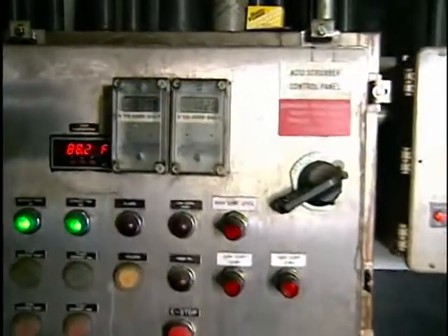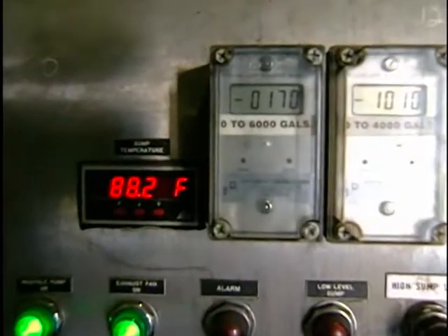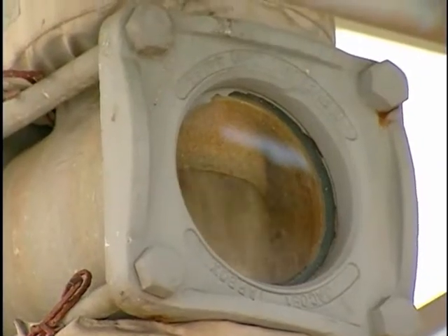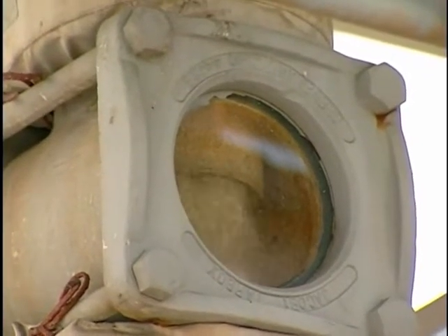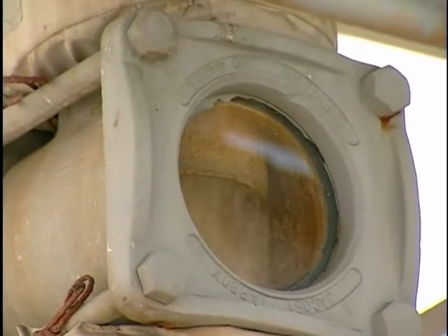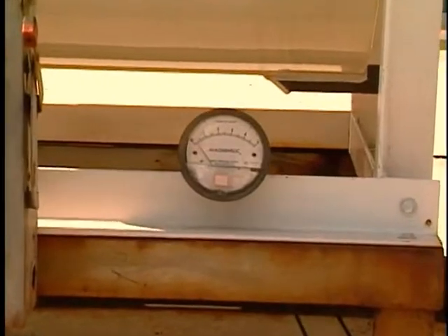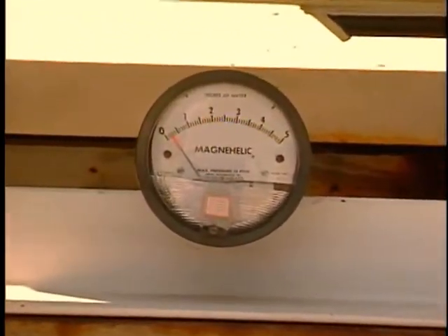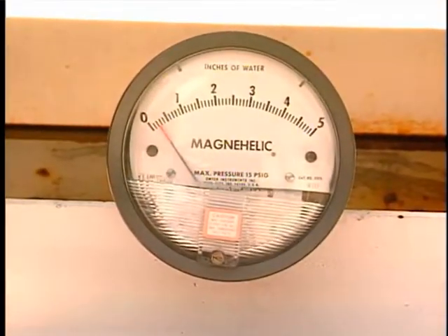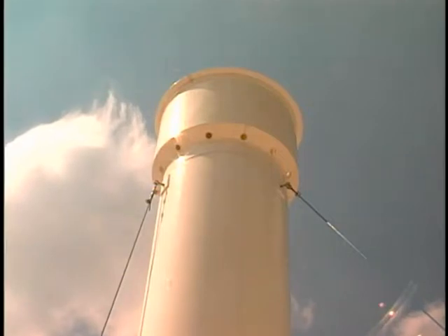The most important factor affecting collection efficiency is the solubility of the contaminant in the liquid. Solubility is a function of the temperature and pH of the liquid. Gases are more soluble in cold liquids than in hot liquids, and less soluble in liquids with low pH. System pressure can also affect solubility, but this is not a major variable in absorbers used for air pollution control, since they operate close to atmospheric pressure.